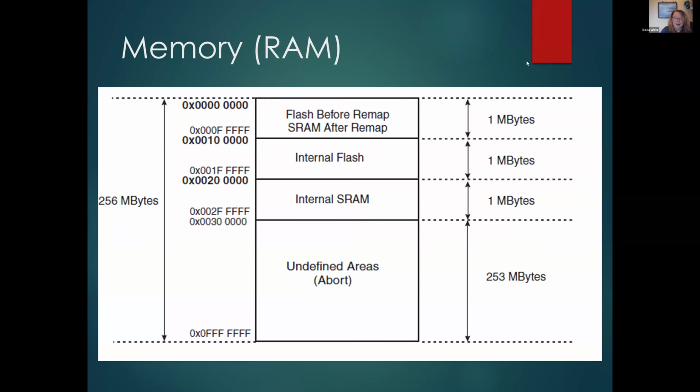Not having enough RAM can be a big shock to software engineers, but it can be a neat puzzle to implement a complex algorithm in small steps using snippets of data instead of a huge chunk in post-processing. And I've heard people squawk, "What do you mean you don't use dynamic memory allocation?" Well, new and malloc use RAM in their implementation. And when you're counting bytes, you need those bytes. And you need to know where all of the other bytes are going. And the way to do that is to allocate everything at compile time.